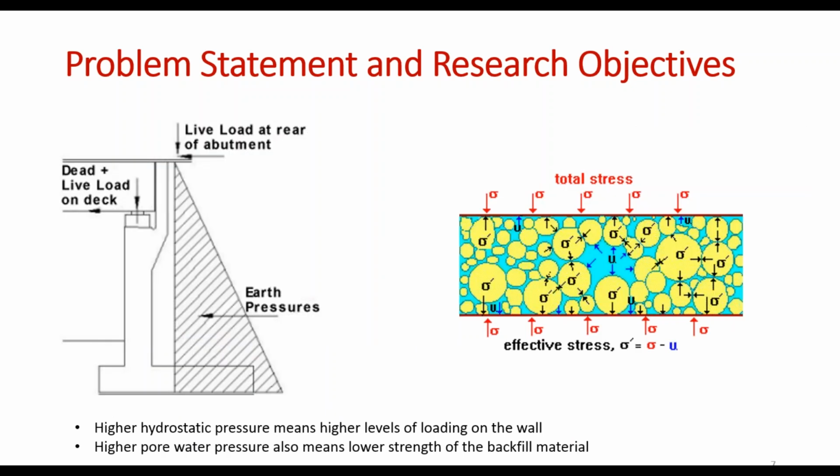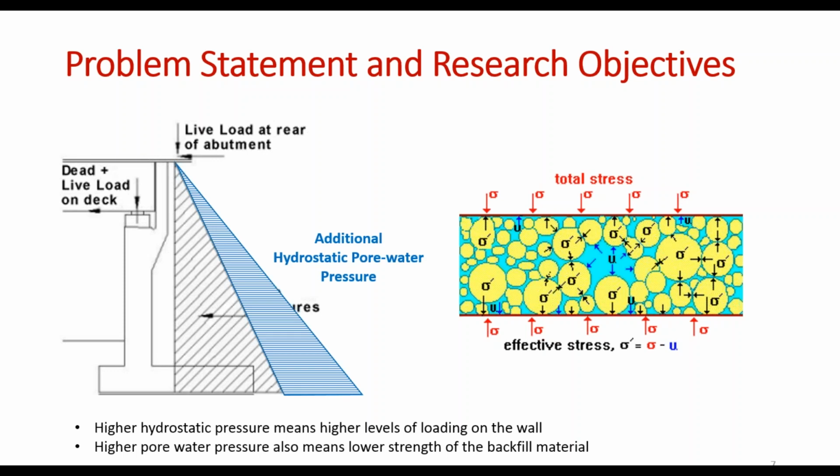First of all, when we design a wall, we have to determine the load acting on it. The majority of the load comes from the earth pressure. But when you have water building up behind it, you have additional hydrostatic water pressure, which will increase the load acting on the wall.